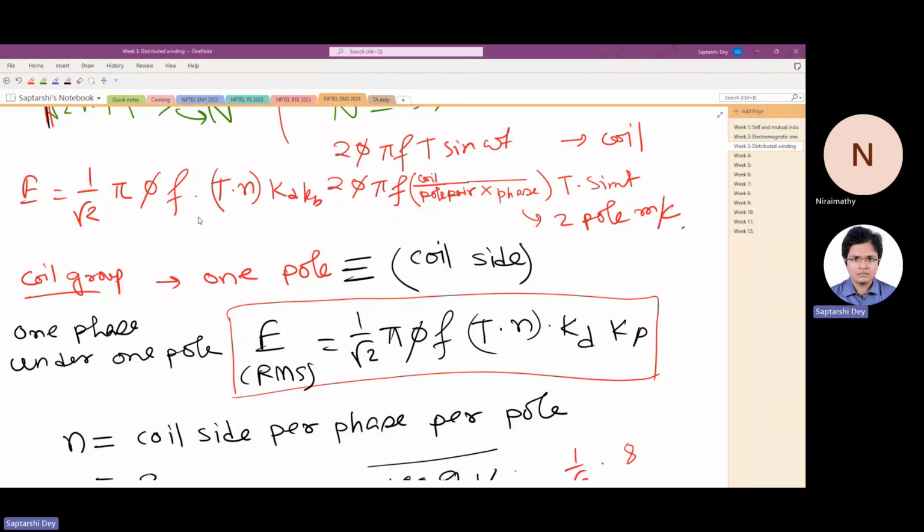There are some innovative indirect ways of finding the magnet temperatures also. To find out the voltage, then correlate with the magnet characteristic to find out how much the magnet temperature is. One of my colleagues did that. The core temperature, anyway, the outside is available to you. Core temperature generally, as far as I know, is not a matter. Mostly we are bothered about winding temperature and magnet temperature. Core temperature doesn't go up that much that it will harm.